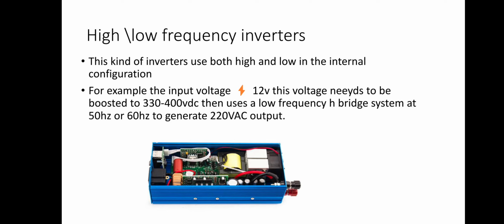Now, one thing I want us to consider on these inverters is that these high frequency inverters you are seeing have some kind of little harmonic distortion. Their signal is not as pure as low frequency signals. It is a sine wave, but there are some kinds of ripples, unlike the transformer based inverters.